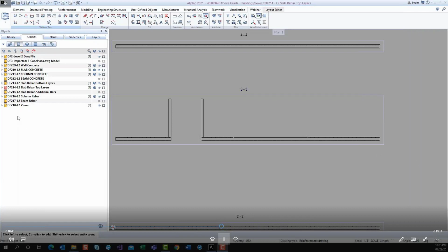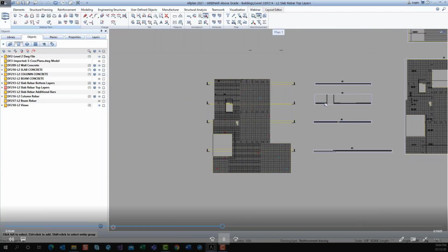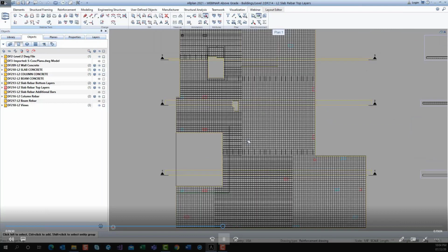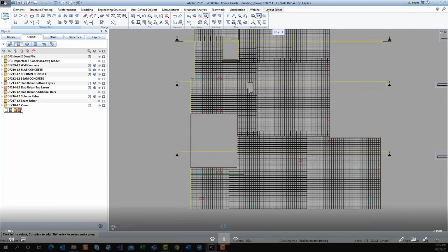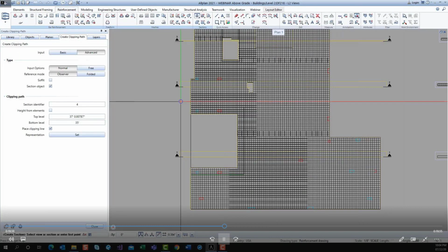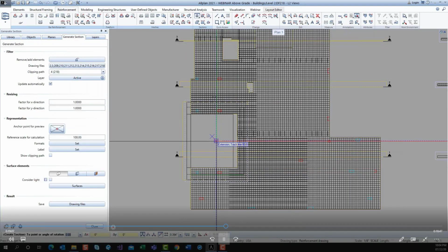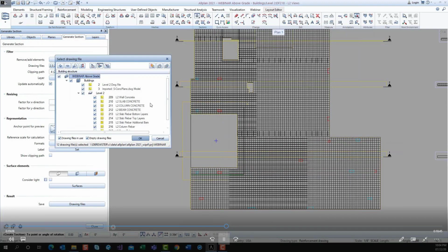So in this next portion, what we're going to talk about is we do have beams. Okay, it's quote unquote a beam, it's a step in the slab. So what we're going to do is create a couple more views here where we're actually going to pop in the beam bars. Now we do have a beam Python part, but I'm going to show you a couple neat little techniques we have with putting in reinforcing your ties and then aligning your vertical bars within that tie.